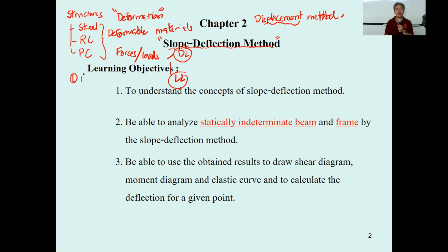One is going to be the building code. That is going to be the legal stuff. You have to follow this code. And most of the live load and the dead load come from the building code. However, the design code that you use in the design of steel from the EIT, Engineering Institute of Thailand, or the ACI, American Concrete Institute, or the Pre-Stressed Concrete Institute, they're going to provide you the design code. The design code is going to give you the load combination that you're going to follow, okay?